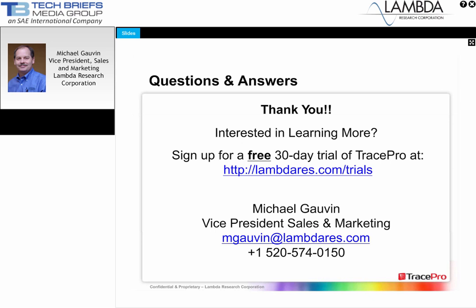Michael, can you define a target light distribution and have the system optimize the reflector to meet the target goal? Yes, very much so. In your merit function, you specify a target surface, and then you optimize to see the light on that target in terms of the distribution that you want. And the program will perturb according to the degrees of freedom that you've given the lens in terms of its variables, and it will flex the design until it meets those goals, if possible.